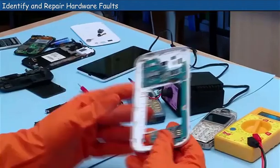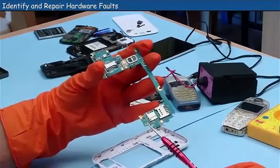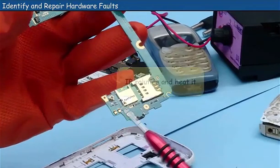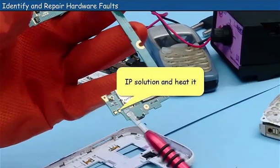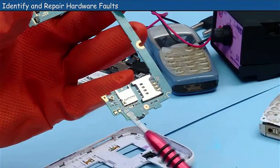To check the hardware component, remove the back case and identify the network plate or antenna of the mobile. Clean the network plate with IP solution and heat it. Then check for the network signal. If the problem occurs again, then check for track continuity. If the problem persists, it's time to replace the network plate or the antenna.